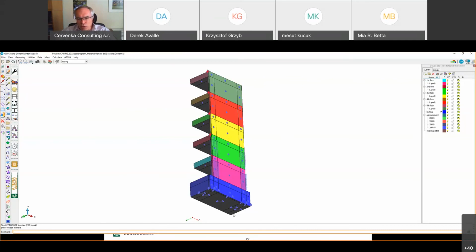Of course, you can also use this first method, as I told you, that you prescribe acceleration at the bottom. But the problem with this approach is that as the acceleration is applied, I'm sorry, the structure will start moving. So it will be moving through your screen. Sometimes this movement may be bigger than actually the relative displacements of your structure. So it is then difficult to see the deformed shape.